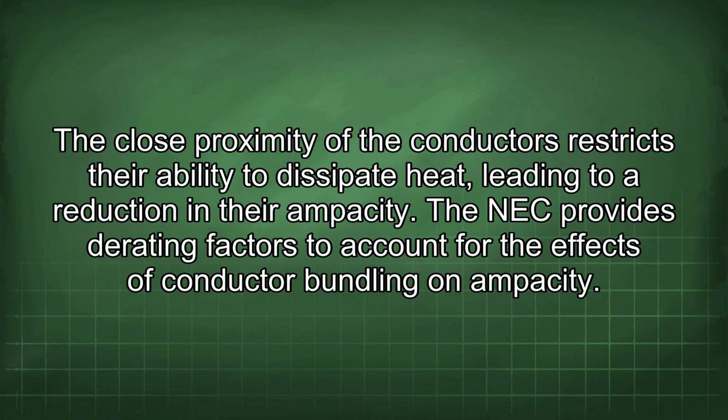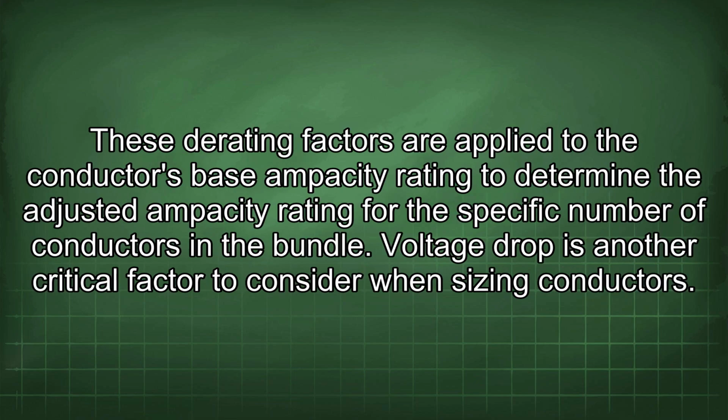The close proximity of the conductors restricts their ability to dissipate heat, leading to a reduction in their ampacity. The NEC provides rating factors to account for the effects of conductor bundling on ampacity. These rating factors are applied to the conductor's base ampacity rating to determine the adjusted ampacity rating for the specific number of conductors in a bundle.